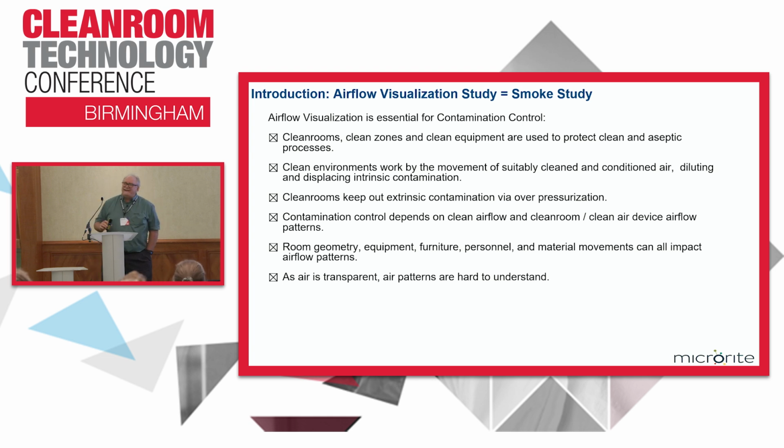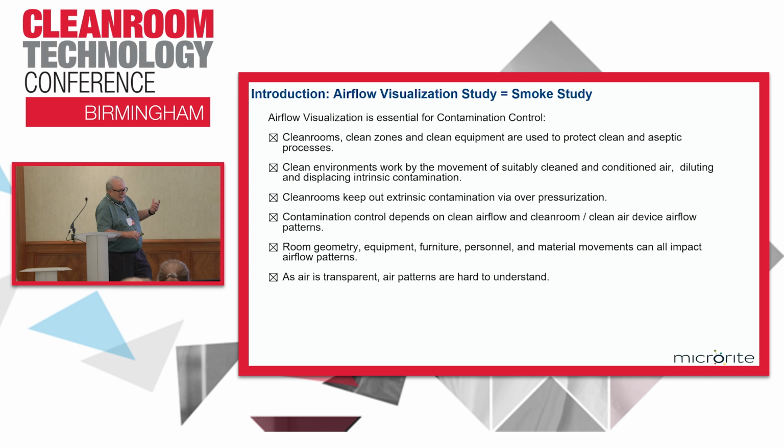Airflow visualization is an essential tool for contamination control. I can't stress that enough. Cleanrooms, clean zones, and clean equipment are used to protect products from contamination. Clean environments work by the movement of suitably cleaned and conditioned air, diluting and displacing intrinsic contamination. We use overpressurization to keep extrinsic contamination outside of the cleanroom. Contamination control depends on clean airflow and cleanroom and clean air device airflow patterns.